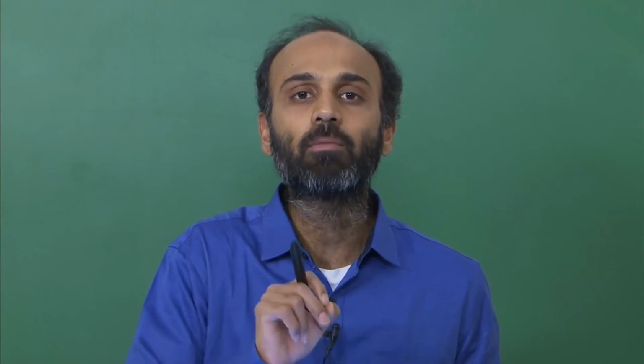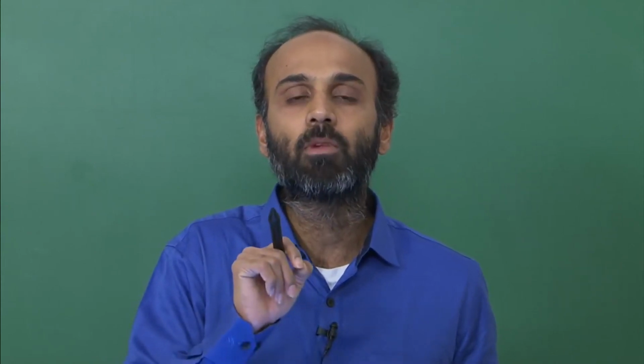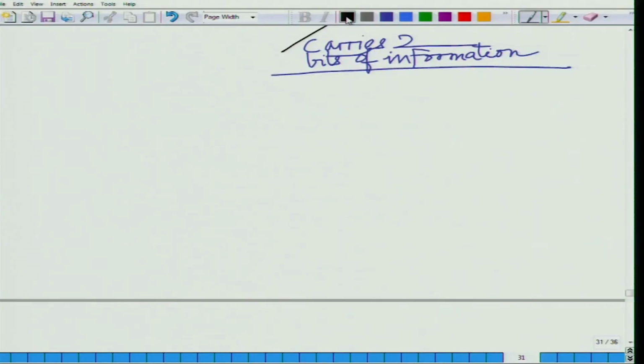These are two orthogonal pulses, unit norm orthogonal pulses. They form the basis, the orthonormal basis of a signal space, which is generated by linear combinations of these pulses. Okay. Now, therefore, the total number of possible signals we have: each of A1, A2 can be plus A or minus A. So, the possible set of signals is A1 equals A.